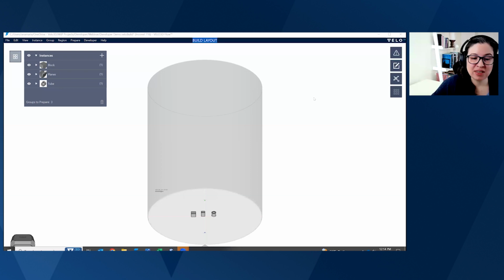And what I have here is our Flow print preparation software. I have already selected the printer that I want to use, Sapphire in this case. And I have already selected as well my material, Inconel 718. Usually when you're preparing a build file, you import your CAD, which I've done already.